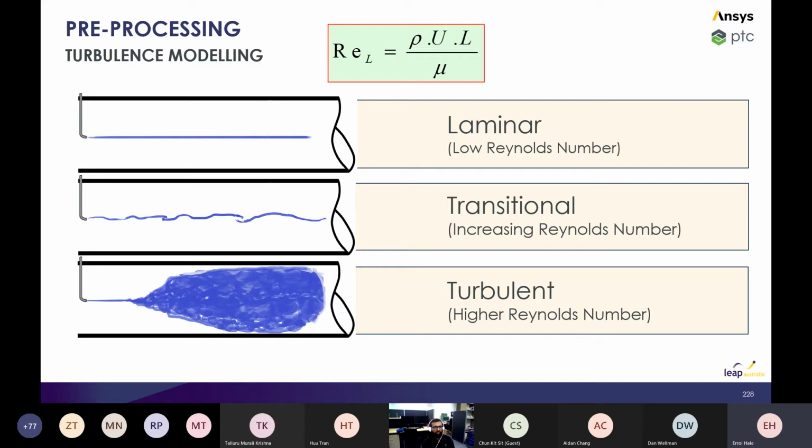And these three things are highly dependent on what's called the Reynolds number. The Reynolds number up here is our ratio between inertial forces to viscous forces. So inertial forces are the inertia of the flow, so the velocity, things like that. You can see that velocity is on top, the density is on top, so our mass, and the characteristic length is counted into the inertial quantities, and it's inertial over viscous, and so below is the viscosity of the fluid.